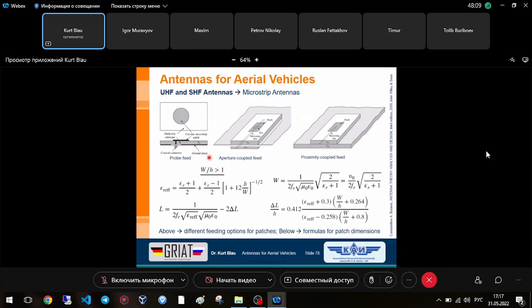Without soldering for feeding, you can see here another possibility. It's named a partial coupled feed. It means we come from the side here. This is this broken line strip. It's a so-called microstrip line. It's nothing else than a strip over a ground plane.